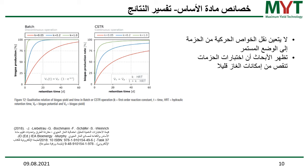So the K value, which is given here, actually rules the fraction of your gas potential you obtain from your process in a certain period of time. The problem is that the K value, which in a chemical process is transferable from a batch to a CSTR system, we haven't found to be transferable in a full-scale application during analysis of lab results.